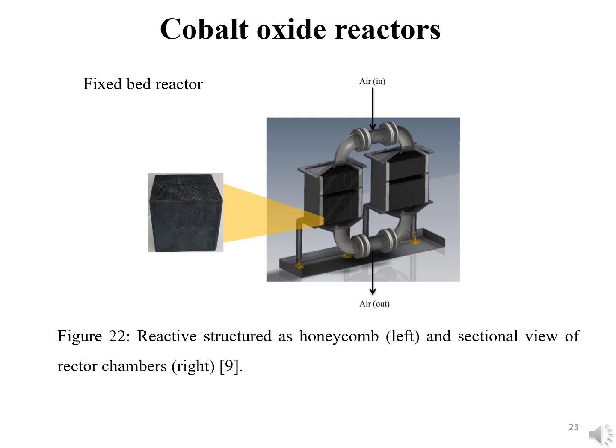According to several researchers, the mentioned problem can be solved by utilizing foam-shaped monoliths or structured honeycomb shapes for the HTF to flow through. These honeycomb structures offer more surface area and effective heat transfer. The proposed arrangement has already undergone a lab-scale proof of concept validation that included semi-quantitative heat effects calculation and their association with redox processes and structural impacts during operation.